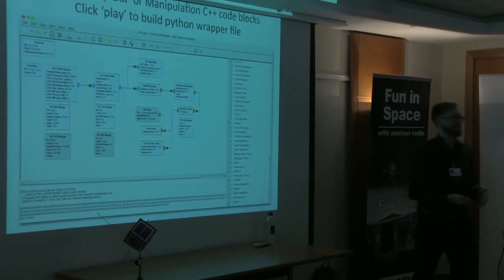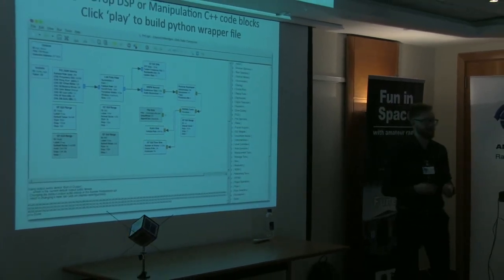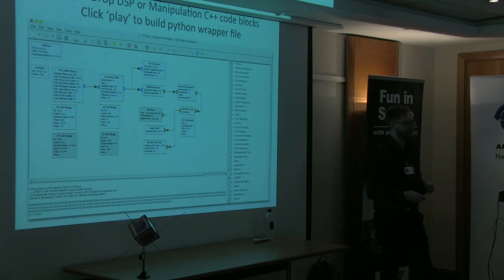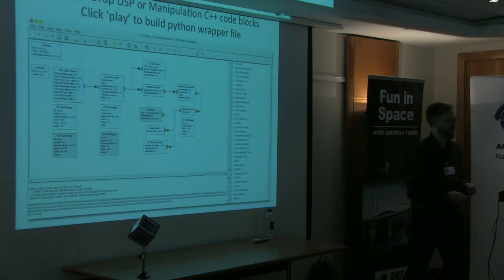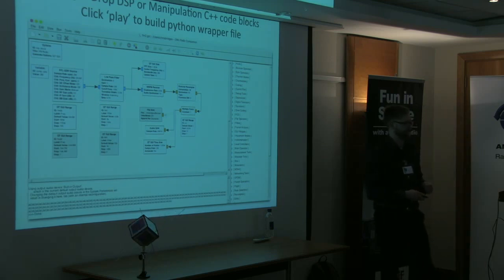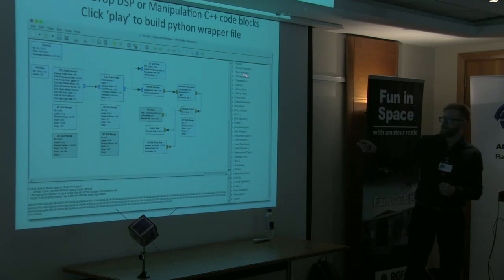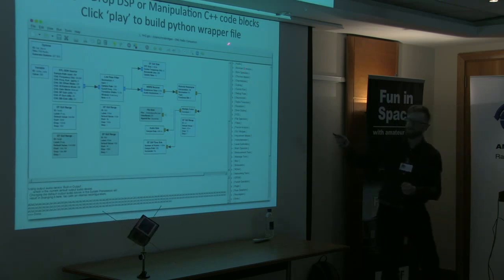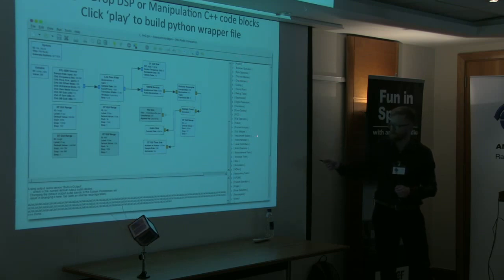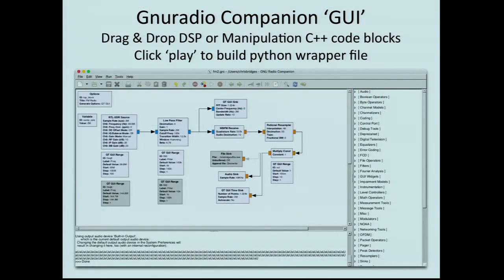99% of these things will want to run on a Unix POSIX system. So that rules out Windows to some extent, but GNU Radio will operate on Windows, albeit begrudgingly. So this is the sort of stuff you can look at. For those of you who can't see it, you've got audio blocks, channel models, error coding, funky dongles, modulators, NOAA systems, OFDM. I'm using it to reverse engineer a DVB-S2 receiver, because there are really no blocks out there for doing all of those video things.